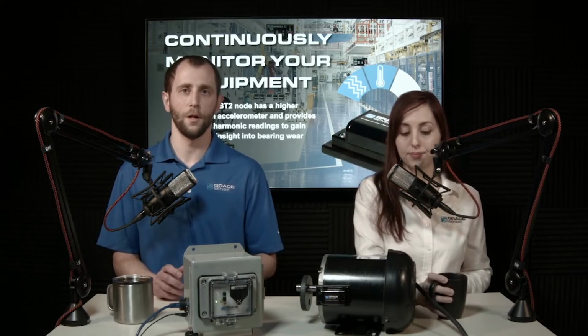These do monitor. It's just there is a lot of work to set those up, from being able to cable everything in. You might have to do new drops of power and Ethernet, and set up everything to where it's closer to the asset you're monitoring. That's a big cost on top, as well as now we have RMS values. What does that mean? If you don't have a vibration specialist on site, you can be getting the overall signal, but you don't necessarily know how to use it.